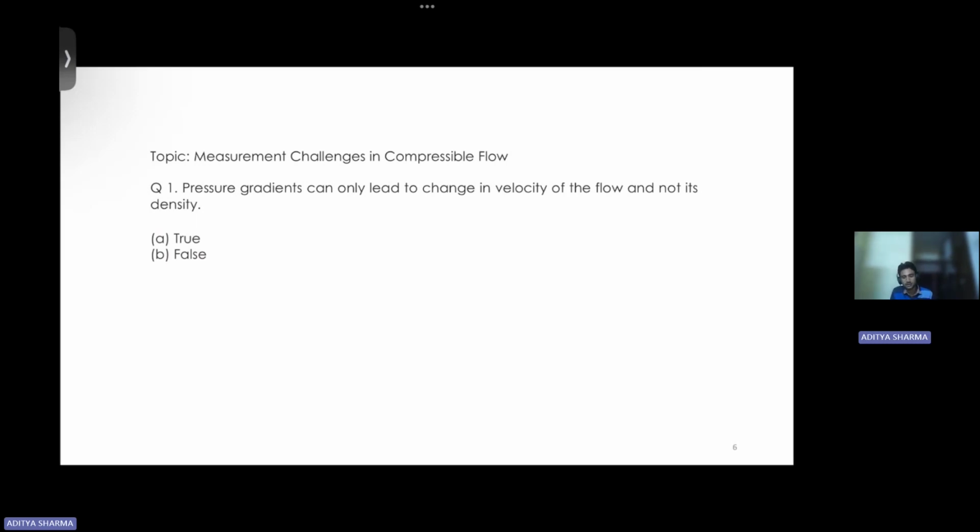So if we see the discussions we have done in previous sessions, if we see the nozzle flow, right? There was also this concept of back pressure, right? Based on the pressure in the reservoir and the pressure at the exit, based on that gradient, we were making our flow accelerate, right? There we see that in cases there are shocks in the divergent section of the nozzle, right? And the flow is also sonic at the throat, right? At times. So if the flow is sonic, it means the flow is compressible, right?